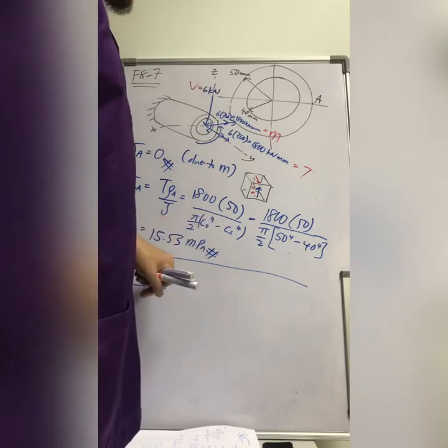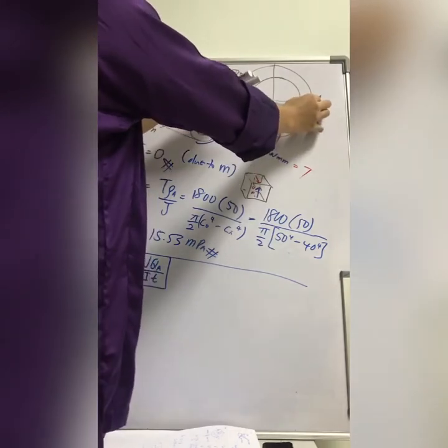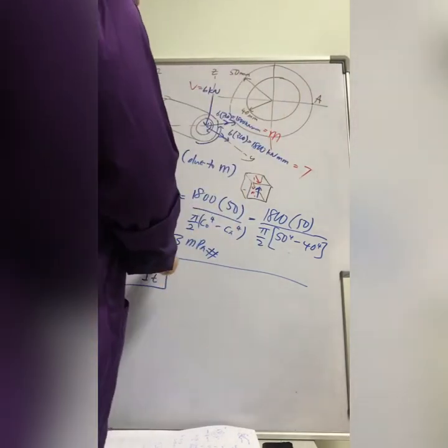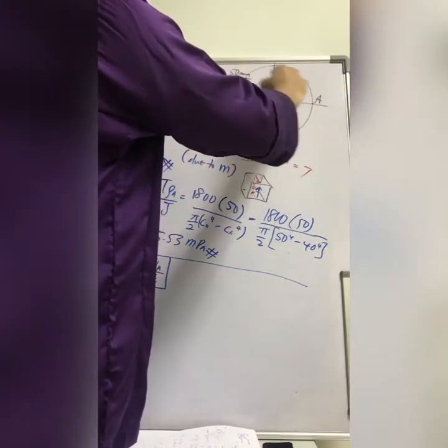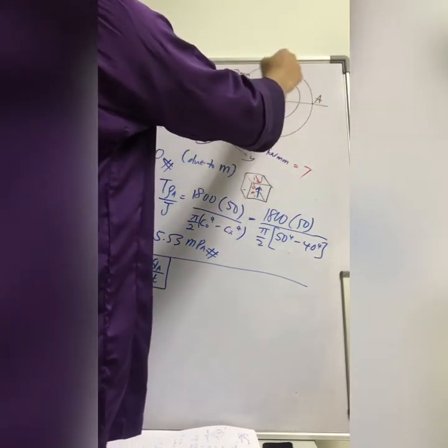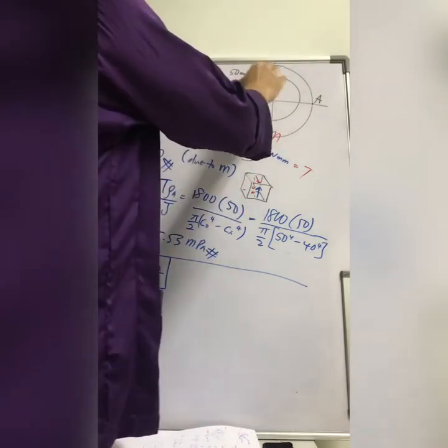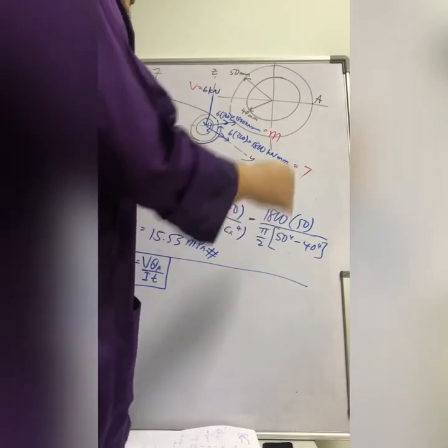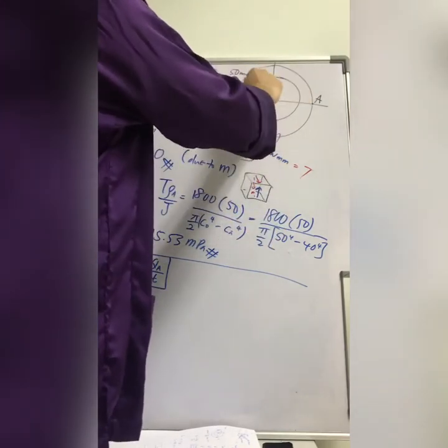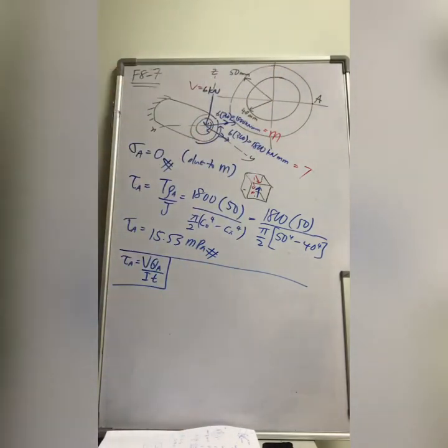It's quite simple. Your T will be this thickness, but in fact you have to take both thicknesses. And then your Q, because this is along the neutral axis, you need to take this minus this. You remember Q is y tilde prime A prime, right? So you need to take this A prime and then minus this A prime. So let's do that.